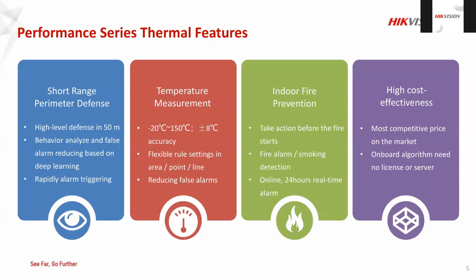What about the durability of the sensor at high heat or high light, or any such quality limit for temperature? Yes, I think it is a very valid question. If you take one of our product sheets, every product, not only the thermal camera, has a working temperature range, the environment temperature in which the camera can be installed. One thing you have to make sure of is that wherever you are fixing the camera, you fix it a little bit far away from the scene. If you want to monitor a storage area, you fix it towards the roof, so the fire-prone area is somewhat far away from the camera.